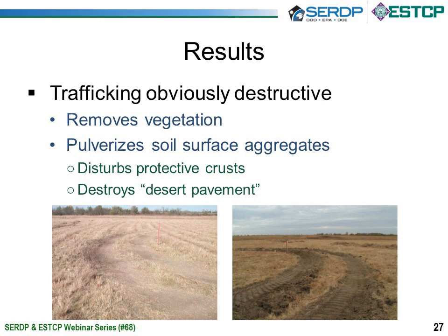Immediately visually obvious is that military trafficking is destructive. Repeated trafficking removes surface vegetation, and severe trafficking can even remove roots of hardy perennial grasses. Once the vegetation cover is gone, the surface soil is continually impacted by repeated trafficking, pulverizing any existing surface aggregates and severely compacting the soil if sufficient moisture exists, as shown in these photos from Fort Riley, Kansas.